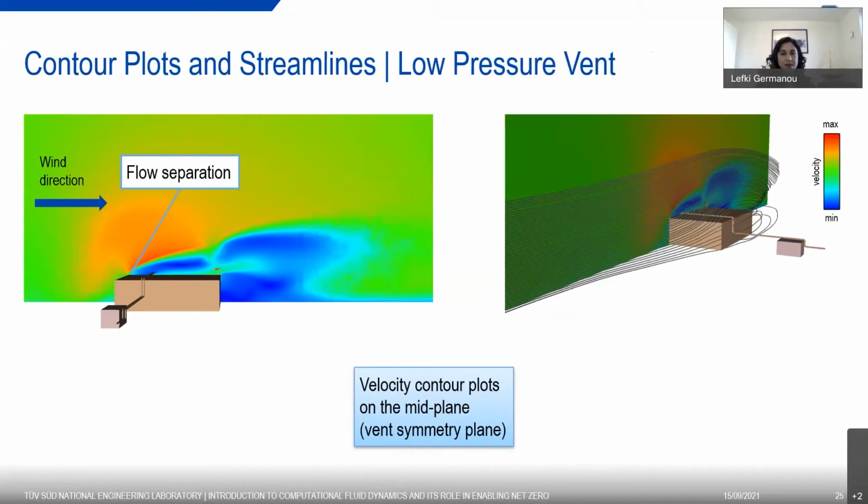The post-processed CFD results indicate that we have a flow separation again as the wind is coming from the wind inlet on the left. And the streamlines show that they cannot follow the geometry of the James Young building, and they go around it and on top of it because it's not a streamlined body.